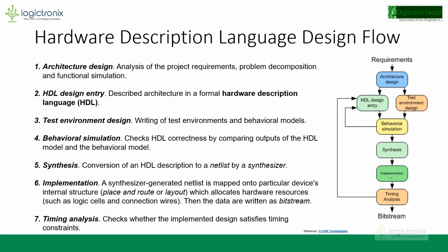This bit file can be uploaded to the FPGA or the array devices, like any specific vendor-based FPGA device. Then we can realize the overall algorithm on hardware. So this is the very basic hardware description language flow, a generic flow. Most design methods on FPGA follow this flow. If we are implementing an algorithm on FPGA or such programmable devices, then you will use this type of flow. So let's go to the next one.